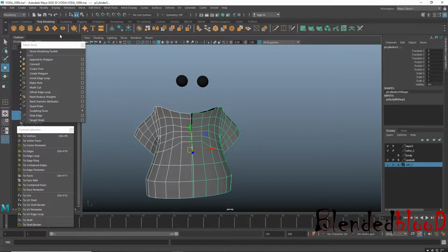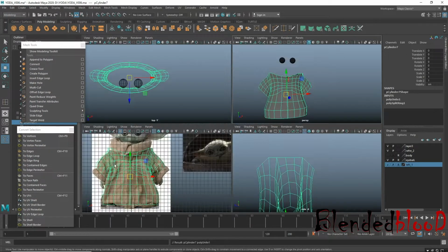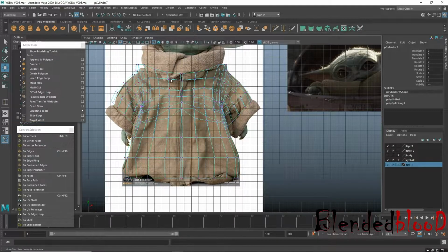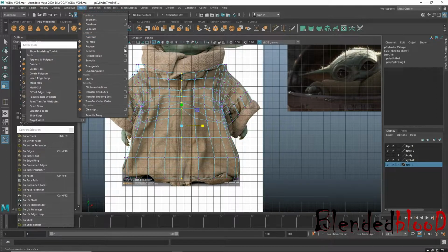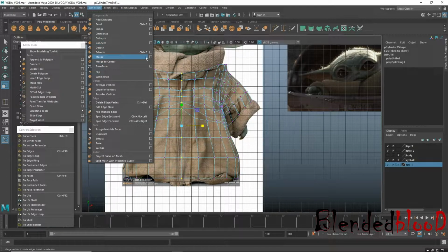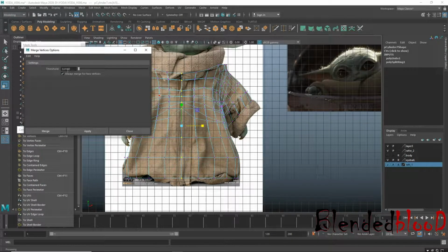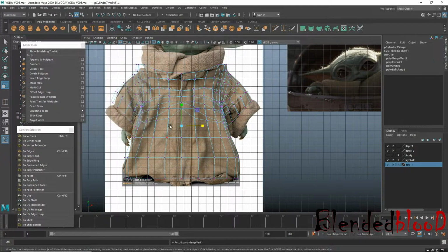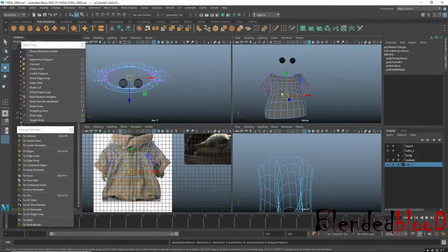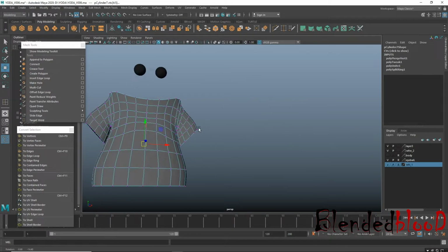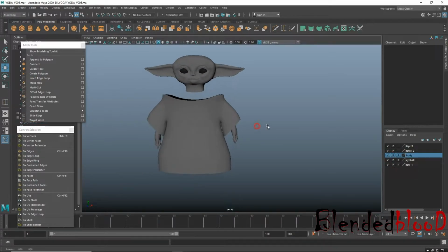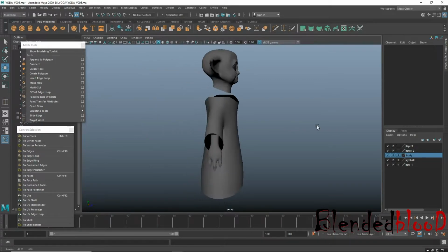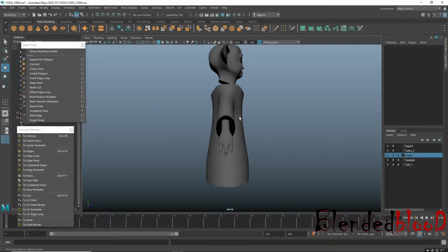Select both, mesh, combine, modify, center pivot. Come here, come to vertex, select like this, scale, now go to mesh, edit mesh and merge, and make sure your value is under 100 and apply and close, that is merged. This one is quite, you can say, a shortcut. See, we are going in the right direction for now, at least.